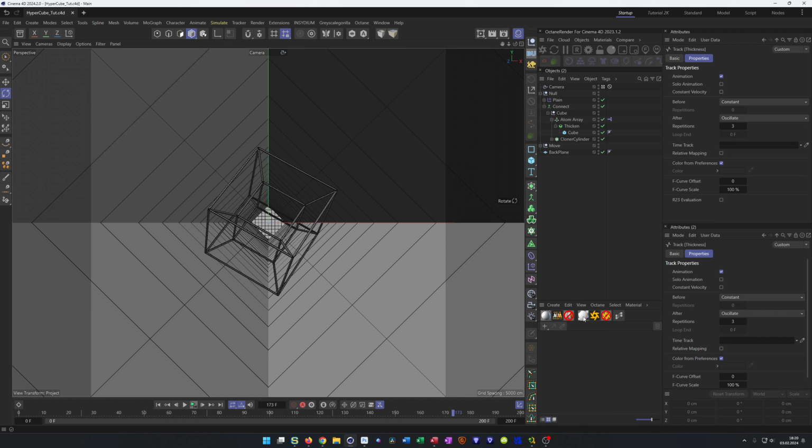So what my first thing was, I make a new Octane material. If you need it for physical render, you can make it exactly the same, but for physical render, you have to give the plane much more subdivisions for the displacement. For Octane render, it doesn't matter. I could do it without any subdivisions. But in the physical render or in the standard render, you need the subdivision. The more subdivisions you have, the nicer the displacement will become.